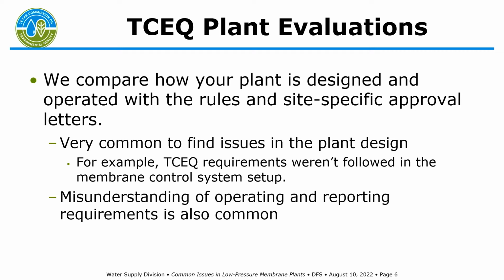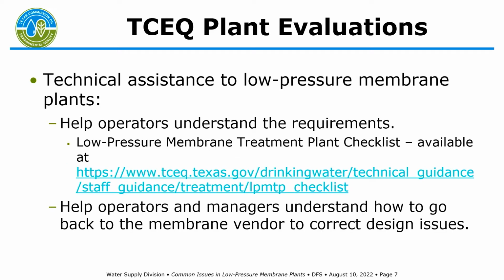The TCEQ requirements for, let's say, turbidity shutdowns maybe weren't followed when the control system was programmed. Maybe you've got something that's not quite compliant. That's pretty typical. Also, misunderstanding of operating and reporting requirements happens pretty frequently.